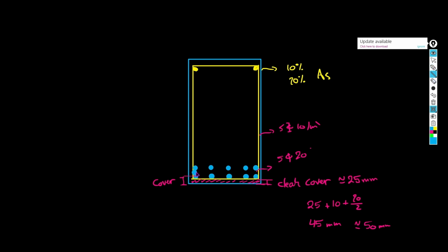Now, if you have more than one row of reinforcement, something like this, something like that. So now you're going to have another reinforcement bar like this, right, to just put these reinforcement bars on top of. And what's going to happen is when you start getting the centroid, now you don't know where the centroid is because it's not here and it's not here anymore, right? What happens is, let me just clear everything. The centroid shifts to the centroid of all these rebars together, which is going to be something like in the middle. So your cover is going to be from the middle centroid until here.